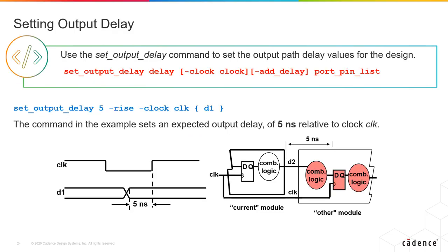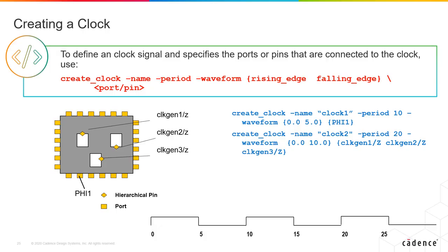Set the output delay using the set_output_delay command for all the output ports in your design. This will ensure that all the registered output paths will meet the timing specified. The tool uses this value to constrain the output ports. The set_input_delay and set_output_delay are used at a block level, in place of the set_driving_cell and set_load commands when you're unsure, or when you are budgeting the constraints based on the modules in the design. The create_clock command creates a clock object with an ideal signal.